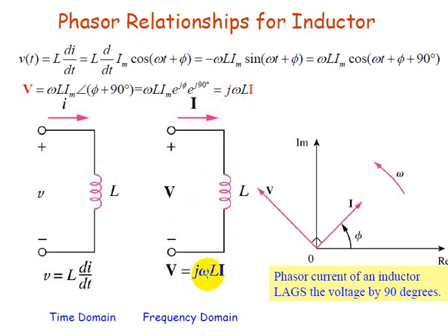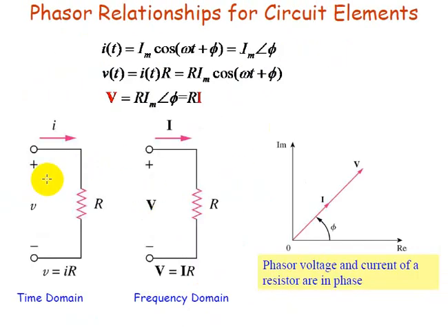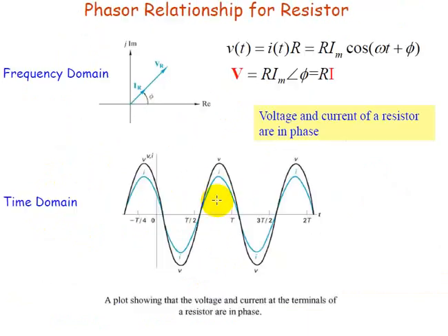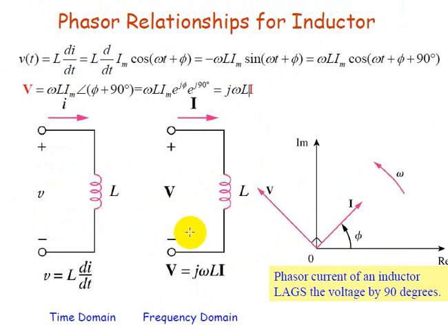Okay, so in a resistive network, the response was R, which is a real value, but in an inductive network, the response is what? The response is j omega L. How have we found this response? We simply applied Ohm's law, which is V by I. V by I is the response of the network, and V by I for an inductor is j omega L.